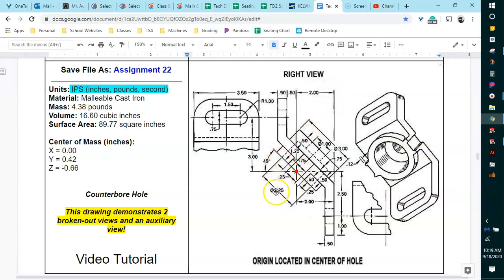So a lot of people would say it's this 2.25, but if I follow where that points to, that is the inside, that is actually the hole that's going to be cut through. So you are actually using this measurement. And I say it stands out nicely because it's not in all of this junk. So it's actually going to be 3, okay?